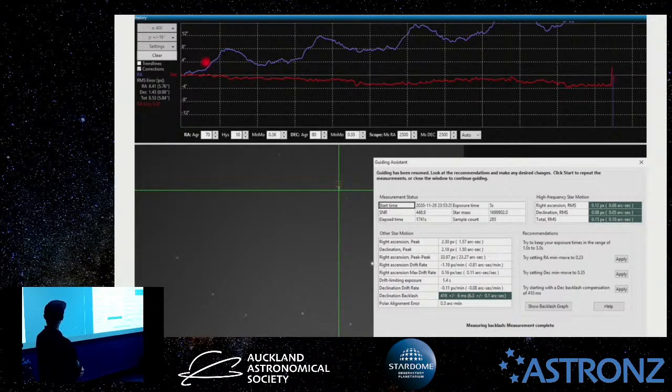This is your RA error, and you can see that it's periodic. And that's pretty normal with our mounts because the gears go round and round in circles and they're not the perfect shape. So the gears will make a bump and go around, then bump and then bump. And you've got probably more than one set of gears in there. So gears add periodic error.